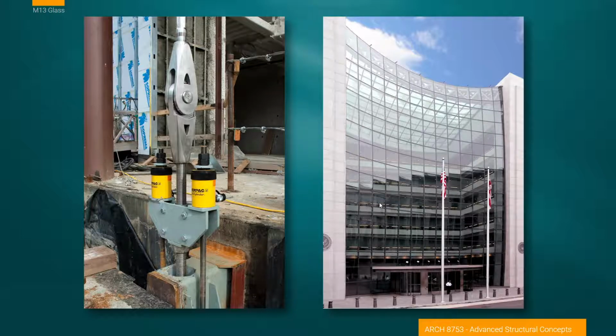I want to spend just a few seconds, because I think it's fascinating, on this cable net system that supports this glazing system, because it's so massive. Here we have huge cable systems coming through, and this is a tensioner for one of these cables. You can see these energy packs are hydraulic systems that are actually built up with pressure in order to pull tension in these cables. And then as they pull tension, the bolt below here is tightened up. So it's a way of putting immense amounts of pressure within the cable system.